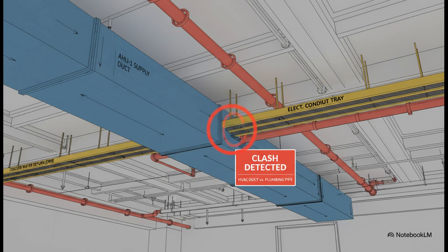Look, even if we're only required to submit 2D drawings, we absolutely have to check our work in 3D. We have to make sure our massive ductwork isn't about to smash into a structural beam, a fire sprinkler line, or a row of lights. Finding these clashes on a computer screen is cheap. Finding them on site after things have been built, that's a nightmare that costs a fortune.